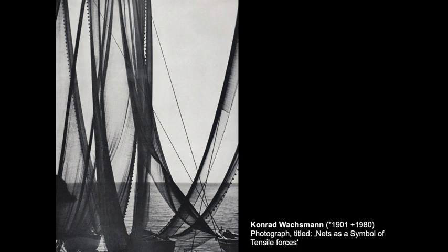Well, the parabolic arch, the pointed arch in the Gothic or the Arabic or the Ottoman pointed arch, this is an old culture of building. It's an old way of dealing with these kinds of forces to have no horizontal forces, which makes it much easier to construct.